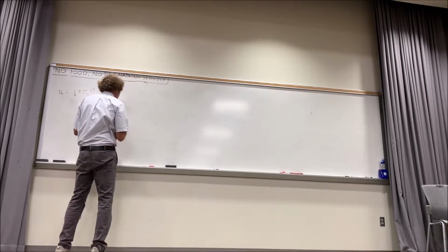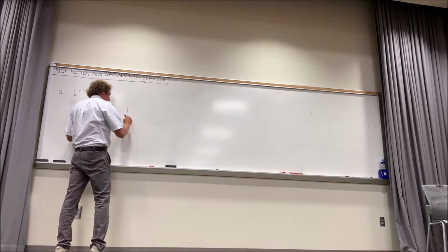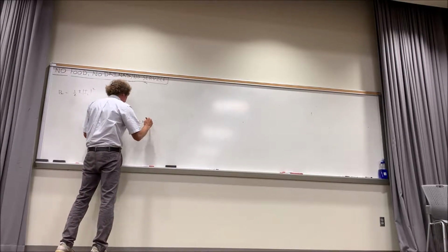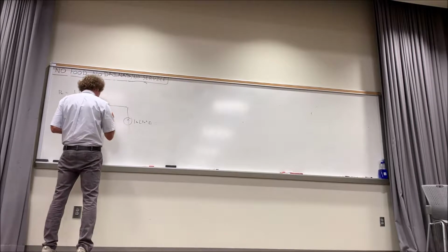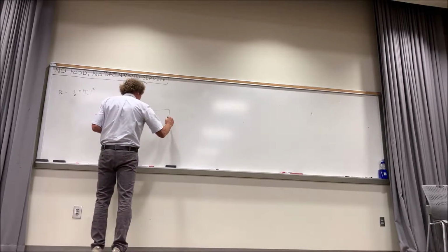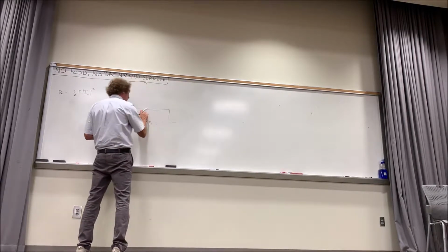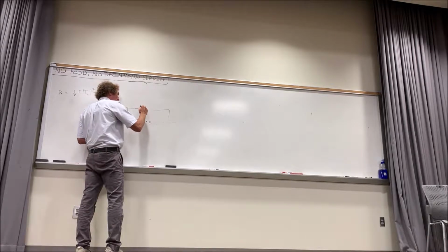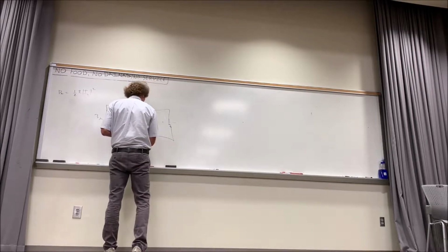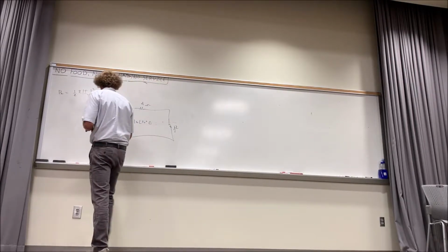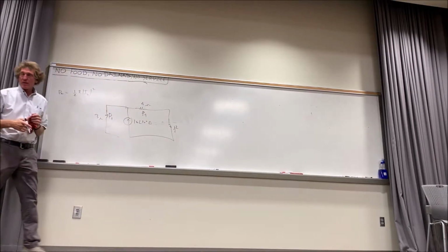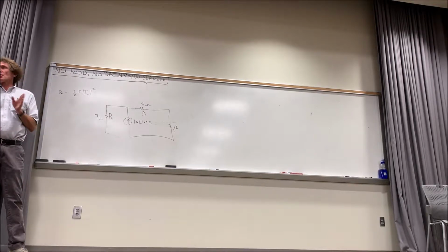All right, let's start with the source. There's a current source in the middle that's 10 amps at angle 30 degrees. To the left of that is a 3 ohm resistor in parallel with it. Across the top to the right, there's a 4 ohm resistor. Down the right side, there's an inductor of j2 ohms. They want to know the power dissipated by the 3 ohm and by the 4 ohm. Remember, class, what we're after is the currents through these things.